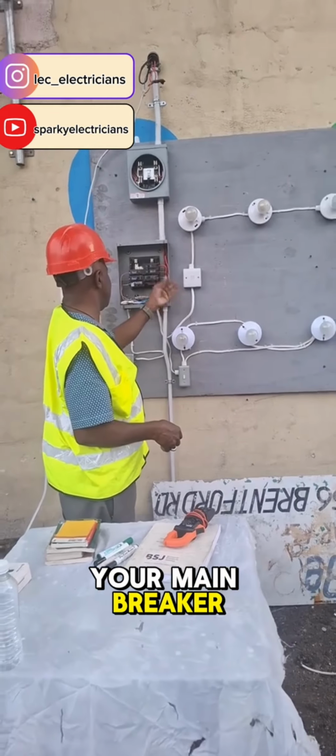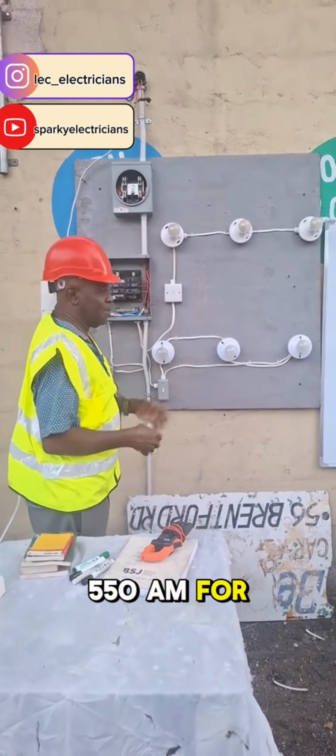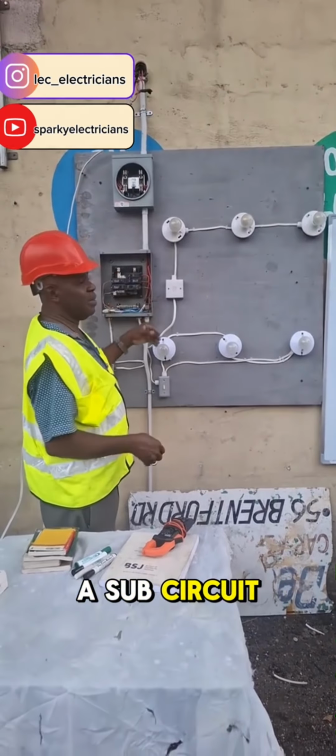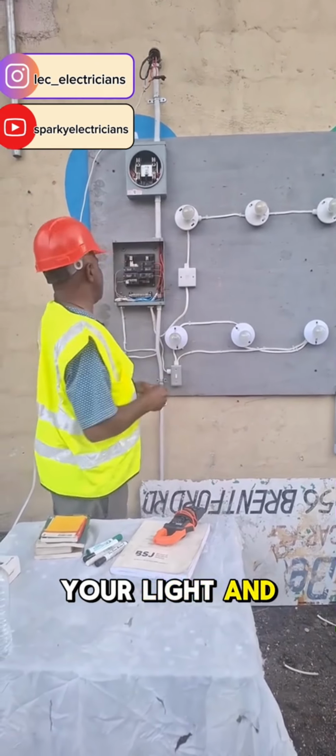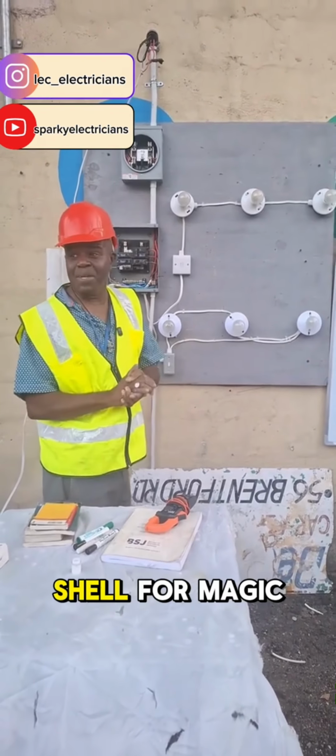You've got your main breaker, your double pole main breaker, typically a 40 to 50 amp for a small home. And you have sub-circuits, a small value of 15 amp for your lights, and 20 amp for your socket outlets, right? So now I'm just going to show you the magic.